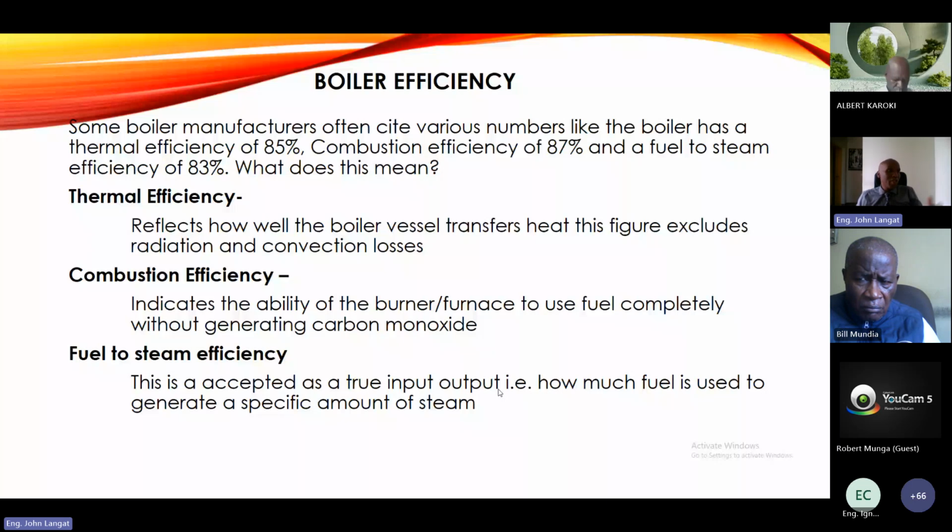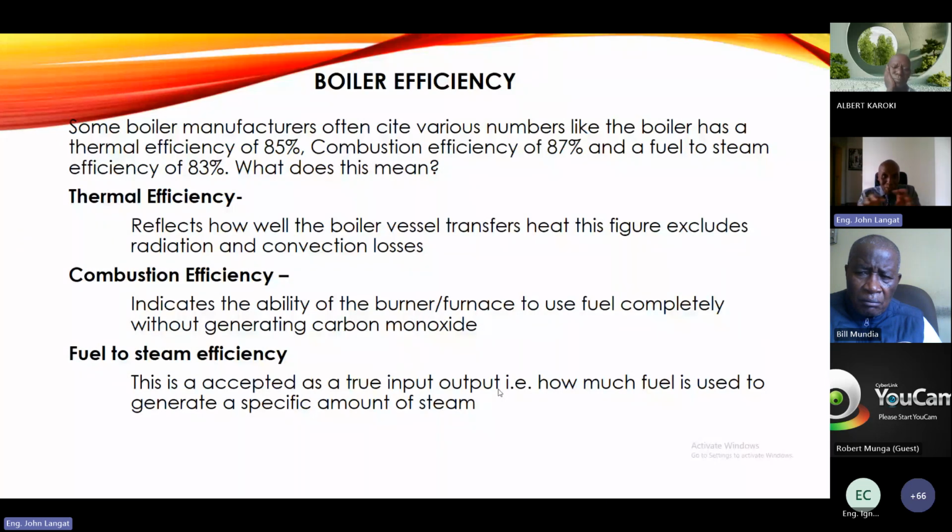And as I was telling you, for thermal efficiency, you will find the boiler operators, because they want to easily operate the boiler without much flow, they remove the spirals. Yeah. Combustion efficiency, you'll find that they frequently open the boiler furnace and let cold air in, then you have excess air on the outside, you have carbon monoxide because of incomplete combustion, or they overstock the furnace until there isn't sufficient airflow. So the boiler furnace starts looking like a kiln, or to put it in perspective, the car kuchoma makaa. If you open that boiler, you'll see charcoal burning inside. That is not an efficient boiler. There is a way of stocking the furnace. You are supposed to leave room for sufficient airflow, so that the stoichiometric combustion happens.